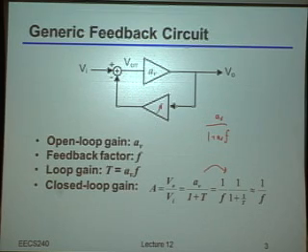So the whole trick here, the whole reason why this buys you something, is that this feedback factor, if you want a gain of greater than 1, is less than 1, right? And it's pretty easy for me to get feedback factors, or gains less than 1, by just doing divisions between otherwise identical components. So if I build this feedback factor out of a resistive divider, capacitive divider, or any other type of divider you can think of, as long as my components match, I indeed can build a very precise division.